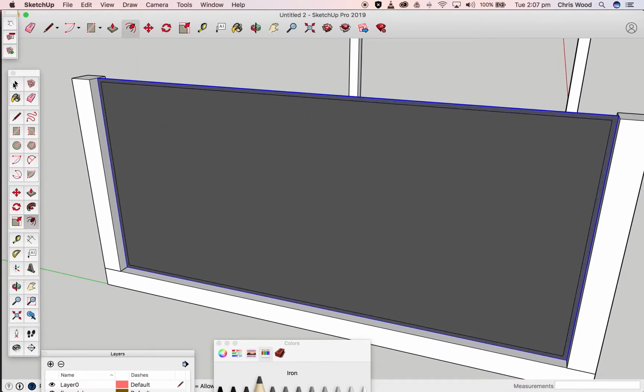And the next thing I'm going to do is break this down into individual sashes. So I'm going to click on it once, and it gives me the full line. I'm using a mouse, so I can right click, and I'm going to now divide this. I'm going to go divide, and as I move my mouse now, you can see it's breaking it down into segments. So width of 1.50 m, that's not too bad. Look, it's an aesthetic decision as much as anything at this stage. So I'm going to go with 5 segments, that's fine.